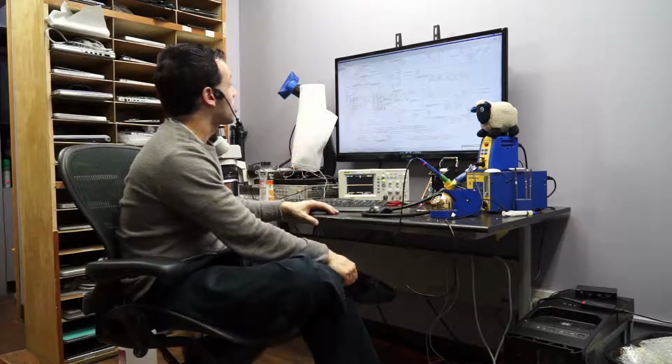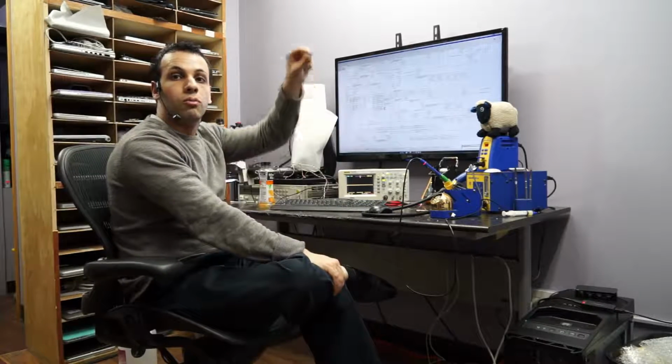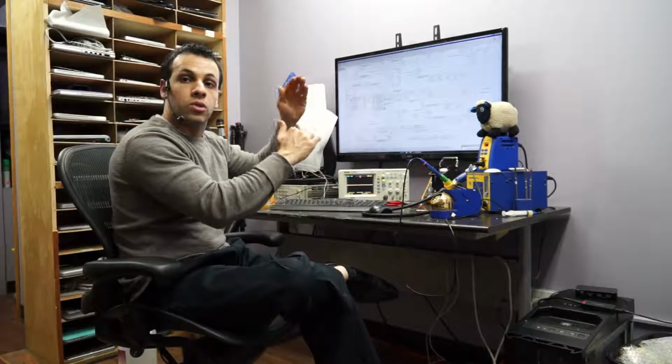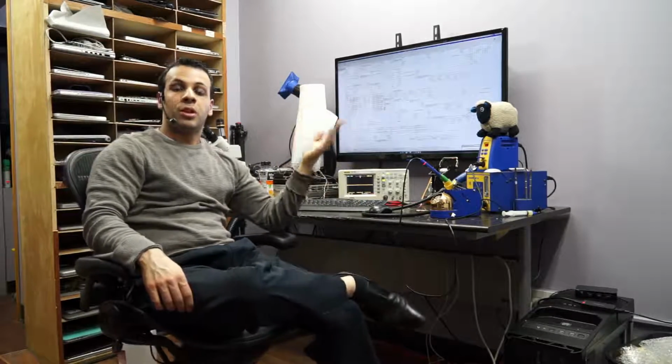So, long story short, you have a resistor in the circuit that's in line with the voltage rail you'd like to measure current usage on. You measure the voltage at the top of that resistor, and you measure the voltage at the other side of that resistor. Those two voltages get calculated by U7000, and based on whatever values they programmed or measured in there, it tells the system how much amperage it's using. If it's using too much amperage, it turns it off.